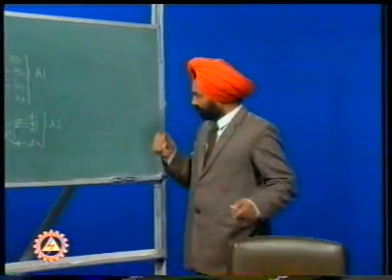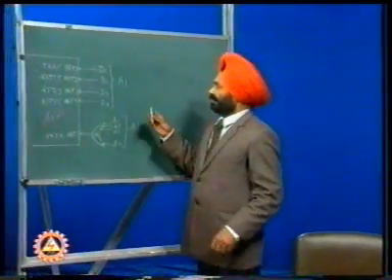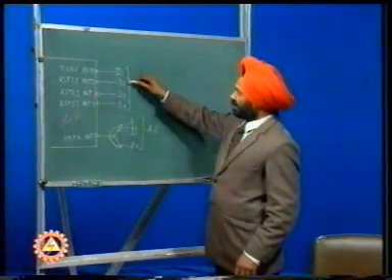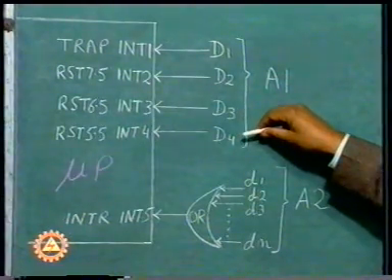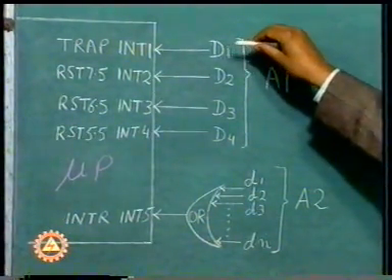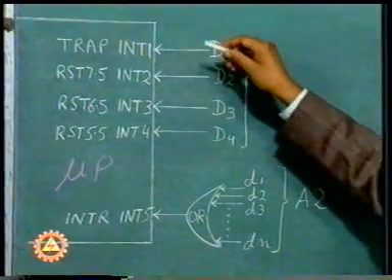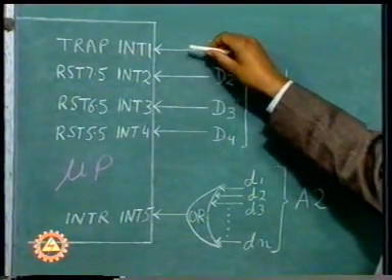To review, any microprocessor may have general purpose interrupts and dedicated interrupts. To see the dedicated interrupts, in schematic A, devices D1, D2, D3, D4 etc. each has a dedicated line of the microprocessor onto which it can send the request.